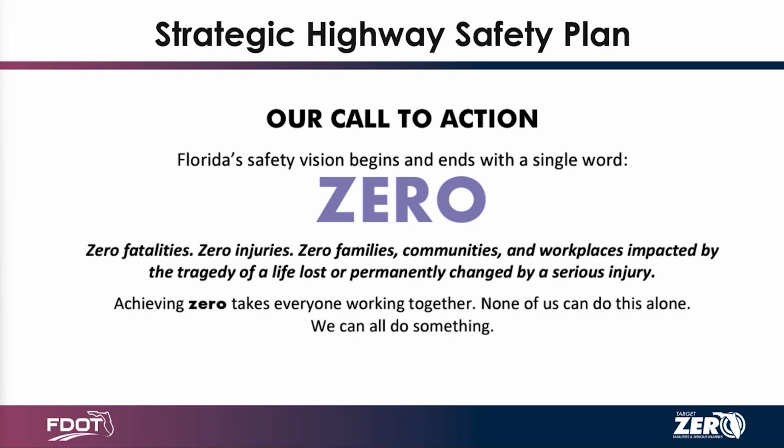There were multiple failure points, right? At that point in time, the water couldn't get off the road. That was a failure point. The concrete pole was too close to the roadway. That was a failure point. The concrete pole wasn't protected. That was another failure point. So you see, there were multiple things that had to happen in that sequence of events for that outcome to happen. So it is something that we do want to pay attention to.